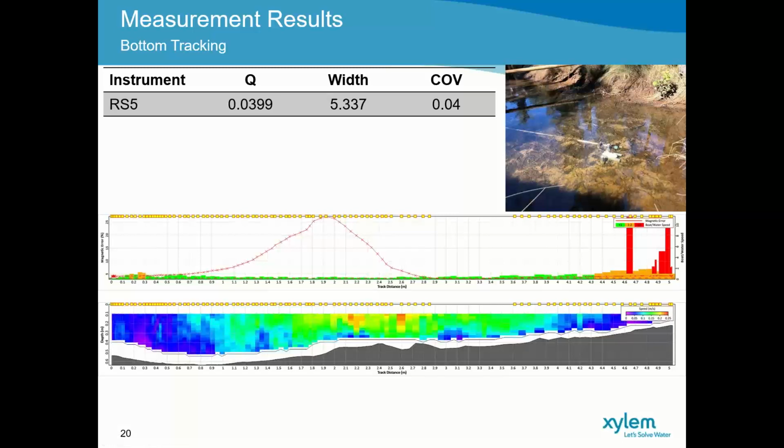It also shows you a magnetic error plot that was recorded, and it works on exactly the same principle as River Surveyor Live, where you have an internal compass. We did the compass calibration, and we measured a magnetic field for every second the instrument moves along.